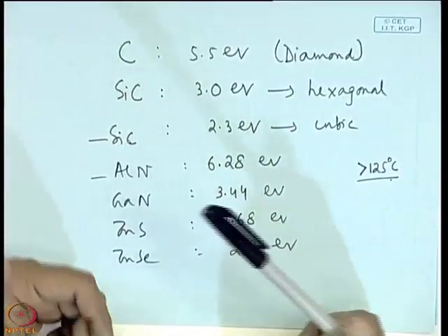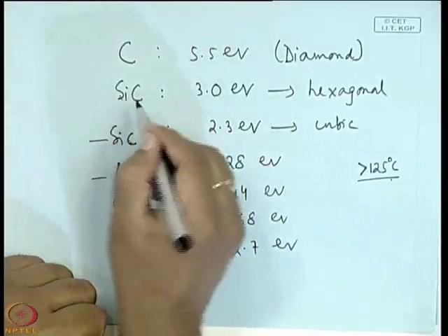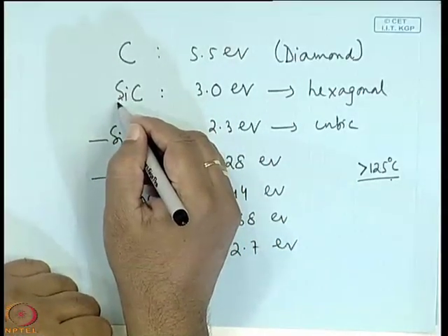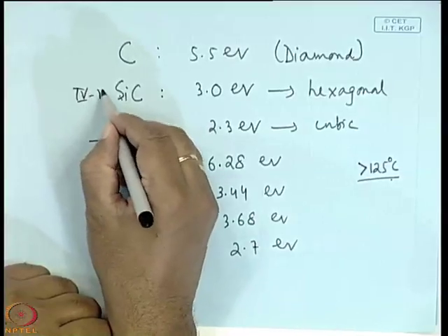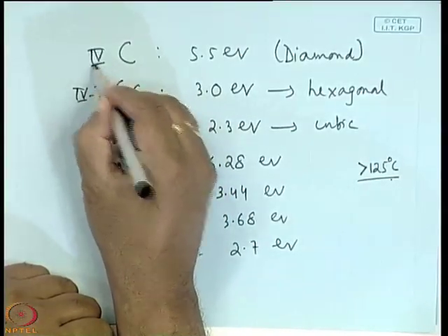If we conclude our discussion, first we took the elemental semiconductors, next we considered the compound semiconductors. For compound semiconductors, we have 3-5, then 2-6, then lead materials, that is 4-6 compounds. Then we have wide band gap, then narrow band gap, etc. In wide band gap, you see that it forms a different group. Silicon carbide, which group? 4-4, right. Then carbon or diamond is group 4.